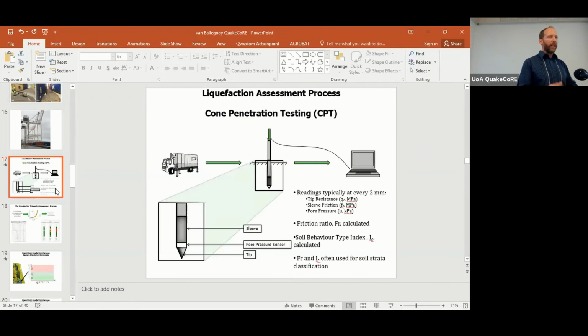And we have seen from the repeated earthquakes that liquefaction just keeps on occurring. It doesn't matter if we've had one earthquake or another earthquake. We had the large February earthquake, then the June earthquake and December earthquake occurred, and liquefaction occurred again. So the relative density of the ground is not significantly changing as a result of an earthquake, and therefore, while the CPTs are all a post-earthquake CPT data set, they are not too dissimilar to what the ground conditions would have been pre-earthquake.